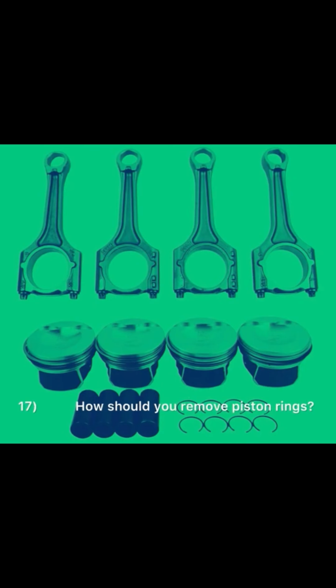17. How should you remove piston rings? Use piston ring expanders for compression rings. Spiral off oil control rings. 18. How are pressed piston pins removed from the connecting rod? Need a special holder. Use a press. 19. How are pistons cleaned?